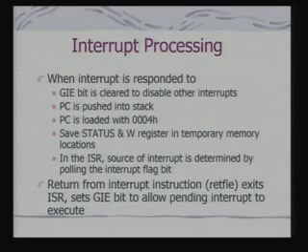Again, here by using your bit check instructions. And when you return from the interrupt, you use the retfie instruction which we had already discussed. This causes the processor to exit from ISR and sets the GIE bit, that is the global interrupt enable bit, so that now the processor can respond to a pending interrupt. And this pending interrupt might have set the flags, and again in the ISR you can check the flag to determine the interrupt.